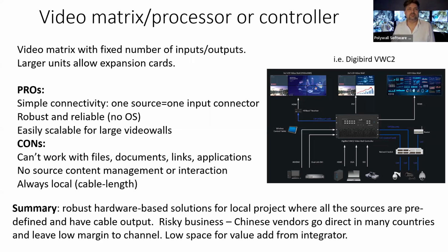The pros and strong points of that technology are, first of all, that it is quite robust and reliable because there is no operating system. There is nothing to fail. It works very well, with fast switching of the sources. It is very simple to connect. You just take a cable from the workstation to the controller or processor and plug it in. That's it. And the same for the panels. You just take a cable from the panel to this device. It is often used for larger video walls because you can insert multiple expansion cards which will accommodate really huge video walls.